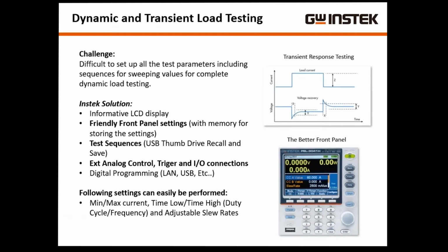So let's talk about the load testing. Obviously, there are 2 types, dynamic and transient. Some of the challenges this presents is that maybe we're not very good at programming, or at setting these types of parameters up. Even though these load profiles look kind of simple to do, this one's very basic, but when you get to this type of profile, where you have a slow rise time here, a slew rate up and down, that's a little bit more difficult to program, right? At first you would say, well, it's challenging, not impossible, but challenging.